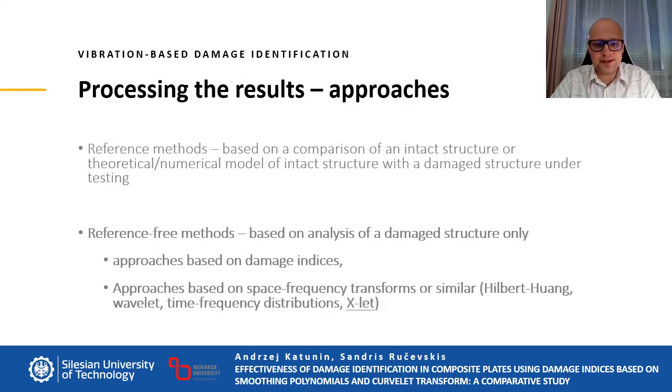In vibration-based damage identification, we have generally two approaches: the reference-based approach, which is based on the intact structure or model of the structure, or the reference-free approach, which is much more effective since we are operating only on a damaged structure.